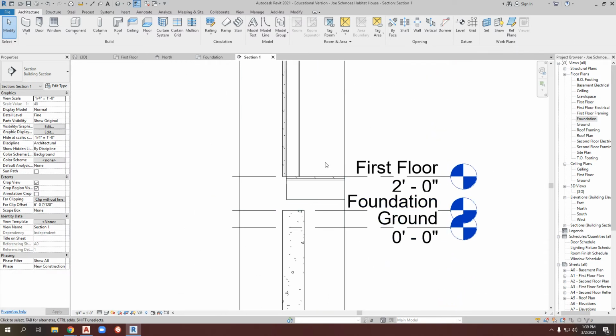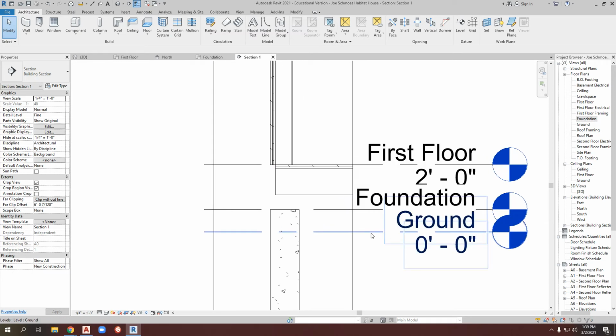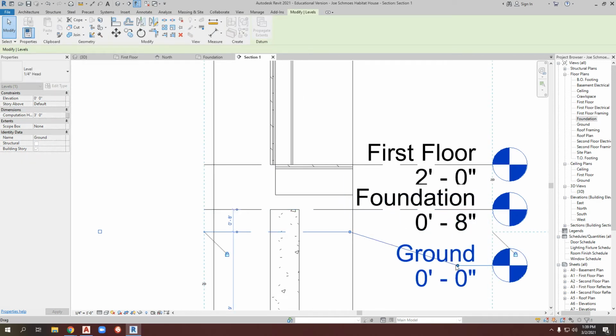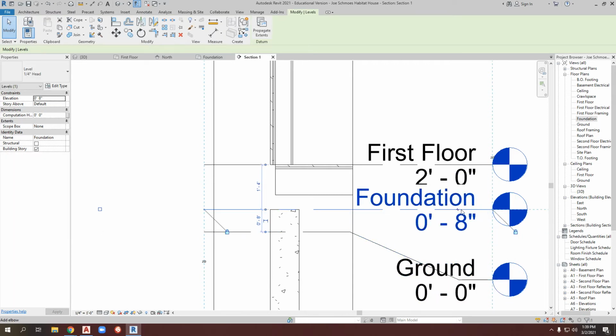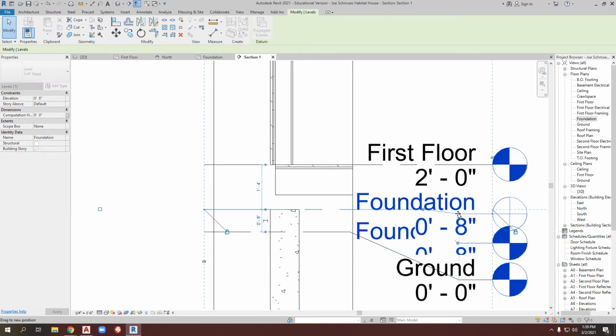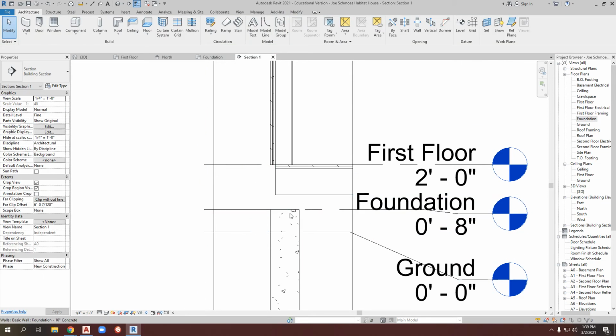And then there is the issue we have up top here. You may or may not be interested in this at this point in time, but we have talked about it in class: how to properly align the floor with the concrete wall and the exterior wall. So I will review that here in this video as well. We talked about needing to place a sill plate between the top of the foundation and the underside of our floor framing. So we talked about going and getting under the annotate.